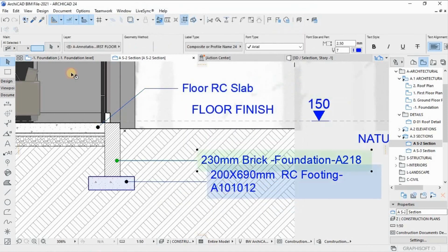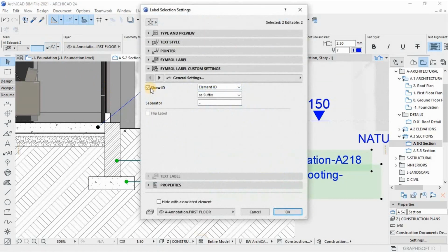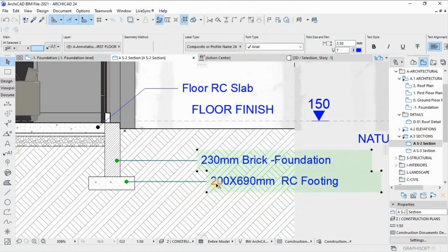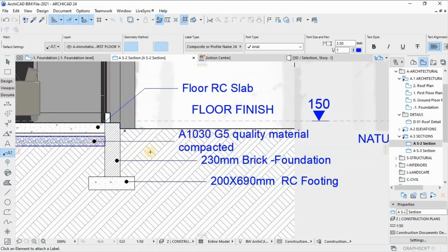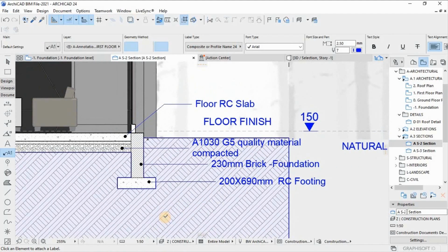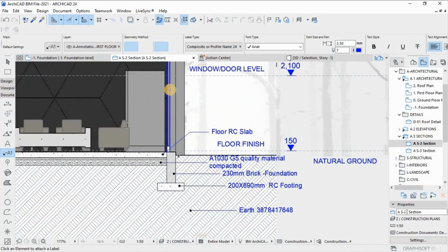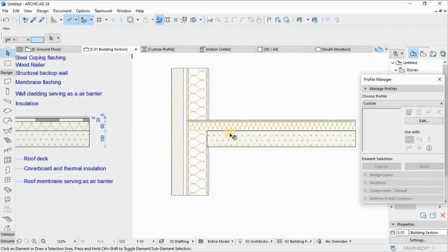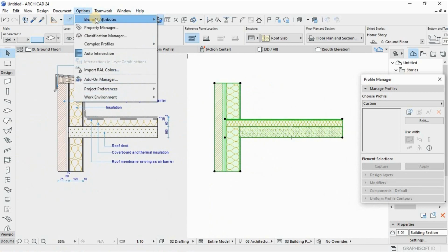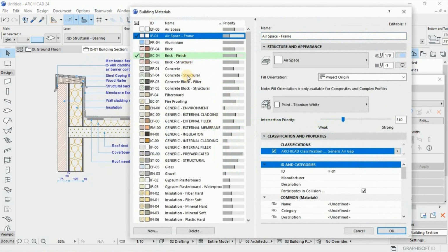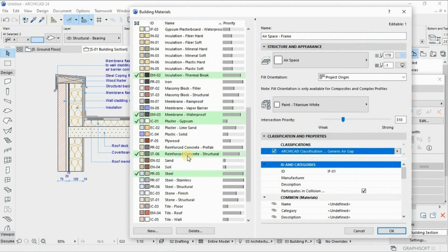Documenting architecture projects in ArchiCAD starts with modeling. The understanding and discipline of modeling for documentation is the key fundamental step to the whole process. One has to model well and then automate the 2D extractions. In our template, to model well, we mostly use composites, building materials, and profiles. The use of these attributes is to achieve the end goal of detailed 3D models and clean 2D drawings.